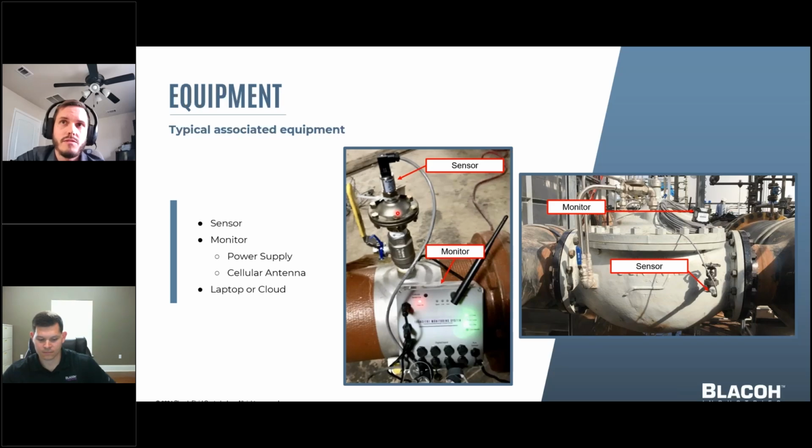Pressure sensors with sufficient update time can be used as long as they are selected with appropriate pressure ratings, explosion proof rating, etc. It can be set up to record at different scan rates. As we discussed, they use different storage methods, whether that's local or to a cloud.